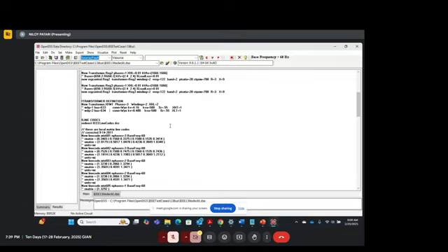Now from the secondary side of this transformer, you can connect like 10-15 houses, or all the customers get their own service. So that is where you have the secondary distribution feeder. So from 480 volt onwards, if you have another connection which connects like 10 houses or 15 houses, then that is the low voltage distribution feeder, or the secondary distribution feeder. And then 4.16 is on the primary.